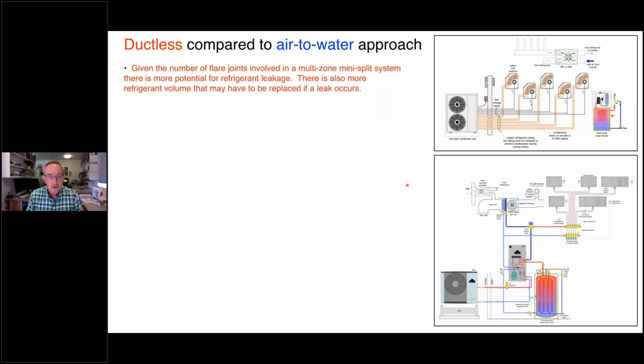With the ductless systems, there's a lot more joints. And in theory, all those joints are perfectly tight. You don't lose one molecule of refrigerant. In practice, that isn't the case. Flare joints that aren't completely tight; with larger systems, if you get into braze joints, they tend to be pretty good, although there is a possibility that depending on how well the brazing was done, that joint could crack from stress. But just think about the number of joints and the potential for refrigerant leakage.